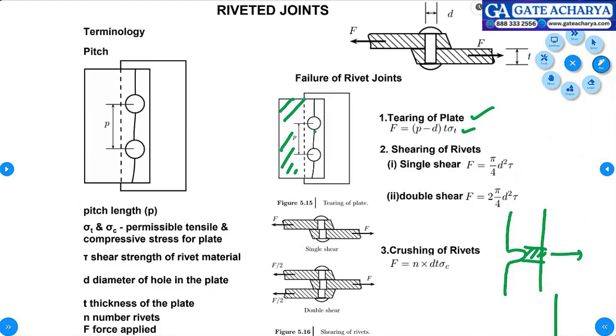Okay, right. So you have any idea? So any component given to you, first you need to have an idea of loading. What are the loads that you are going to come across? This is number one. Then you need to have an idea of what are all the failures that you can come across, what type of stresses are getting induced. Then you need to have an idea of which theory to apply. Then get whatever variable you want, thickness, diameter, life, factor of safety, whatever you want, you get it.